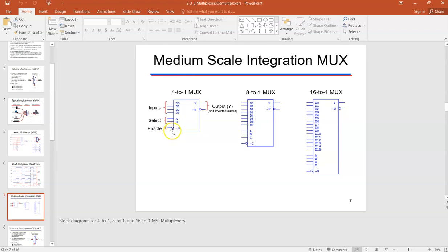Notice that little circle, it looks like an O or 0, right there on the pin. That is because this has a built-in inverter. And so you actually need to send ground. That'll invert to a 1 to enable. So this enable has to be grounded. For your output, you have both the output and the inverted value of the output available to you.